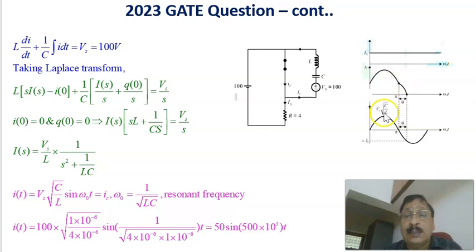This is the load current, which is equal to 100 divided by 4, or 25 amperes. This one plus this equals that. This is the total current to the device. Therefore, even though the current through this path is going to zero, there is still a current through the device because there is a load current. That is why there will be current.